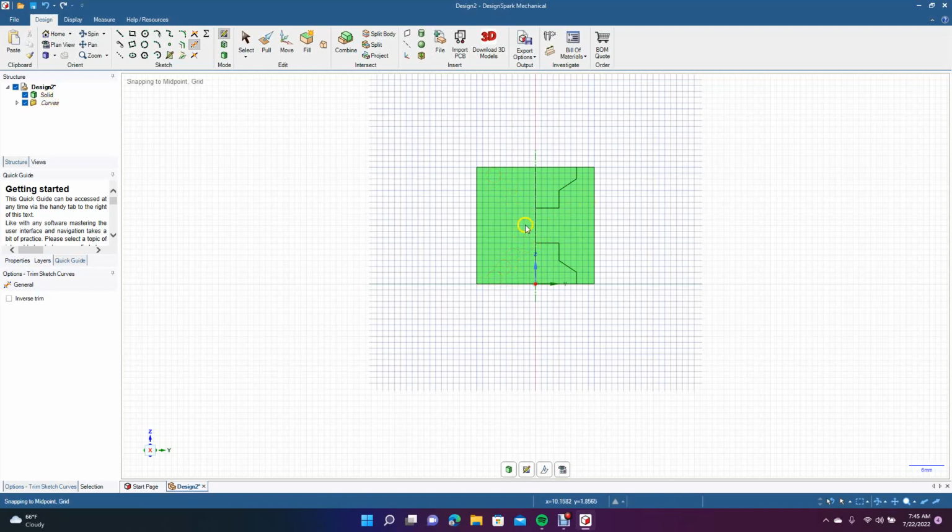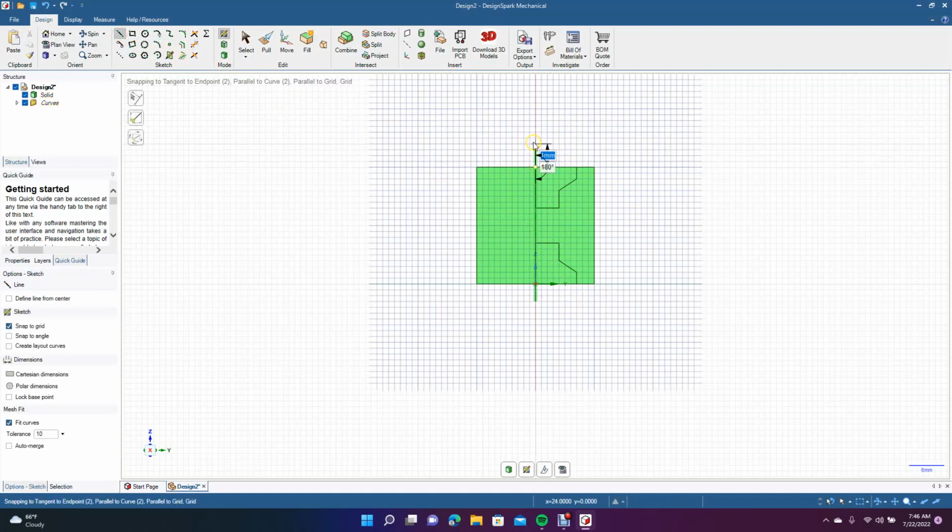And remember what I was saying earlier about making sure to draw your shape outside of this shape so it'll be easy to select. That's not a problem. We can go ahead and add up to here like this, and then we can get the line tool and add some more length to here, because this isn't going to really matter. This is just an area that's going to allow you to select it, because once it's inside of the sphere or this round cylinder shape, it's going to be hard for you to select it to do the revolve. So we're going to go pull.